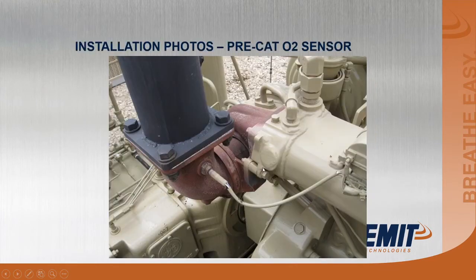Okay, another look at it. Your O2 sensors, you always want to install them as close to the engine as possible. The farther you get in the exhaust stream, the bigger the control loop is and the less stable your system becomes. So we usually like to put them right here. This happens to be a little 3306 turbocharged Caterpillar, and there's a boss on that elbow, and it's either going to have pipe thread in it or there's no thread in it at all, and we drill them out and tap them to 18 millimeter.